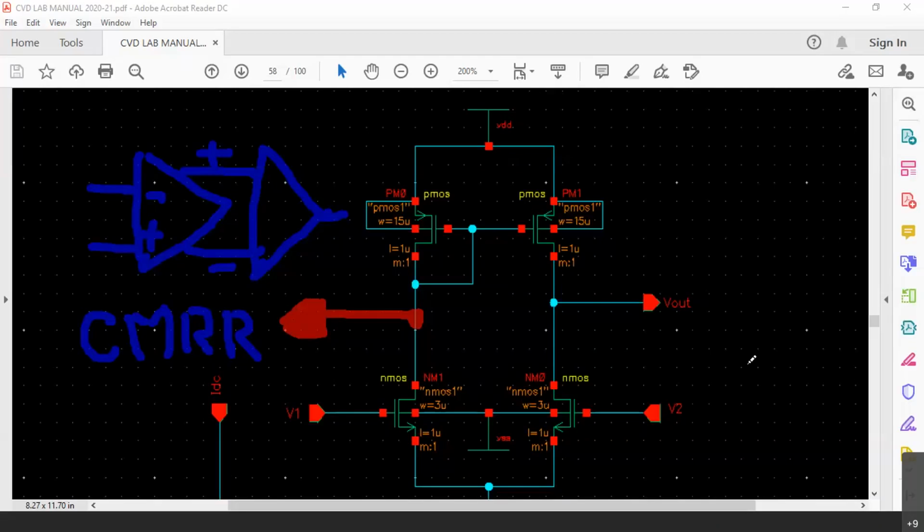Later on, if required, when you come to final year, you can take up this design seriously and you can design an RF amplifier. Even now people are working heavily on RF amplifiers having higher gain and higher bandwidth. You know that in the case of MOSFET, as we have a lot of parasitic capacitances, obtaining a larger bandwidth is a challenge with MOSFETs.